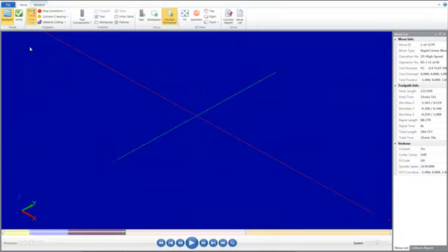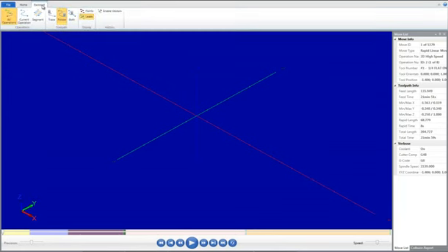Backplotting shows the path the tools take to cut the part. This display lets you spot errors in the program before you machine the part. As you backplot toolpaths, Mastercam displays additional information such as the X, Y, and Z coordinates, the path length, the minimum and maximum coordinates, and the cycle time. It also shows any collisions between the workpiece and the tool. From here, select the Backplot tab and ensure that the following settings are enabled: All Operations, Follow, and Leads.